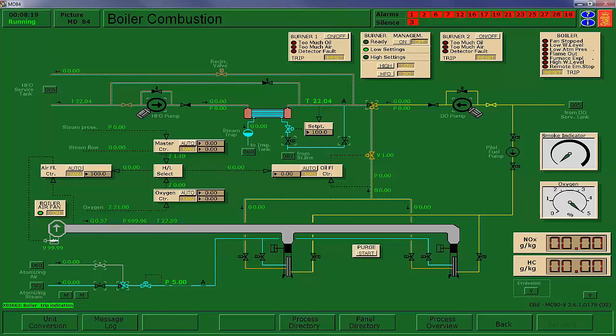We've done our purge. Now, go ahead and bring your damper down to about 9%. And then watch your damper drop down here. By the way, this will not go below 3%. It will never close the dampers all the way, to try to maintain a fire. On your firing rate, we'll set initially at 15%.